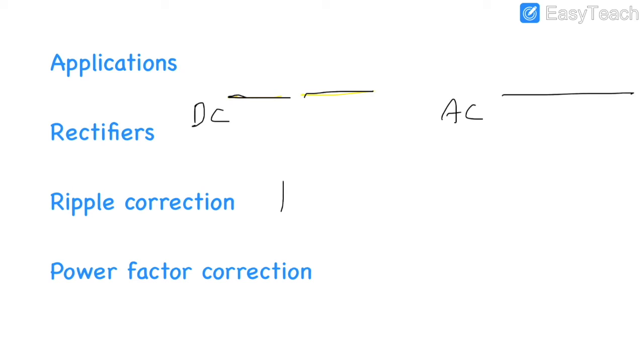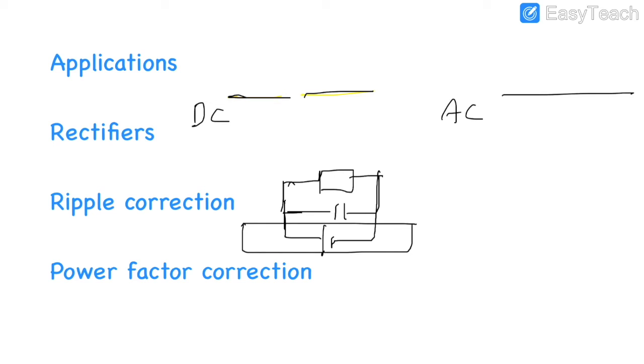So let's say you have a load powered by a DC supply, and then sometimes your DC supply can fail. In case your DC supply fails, your capacitor is still charged. Let me use a different color for the part in the box. So let's say the part in the red box fails, the capacitor can still power the load. So there's no ripple, and the voltage to the load is pretty much a steady DC.